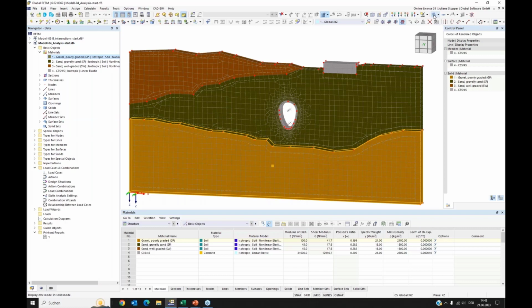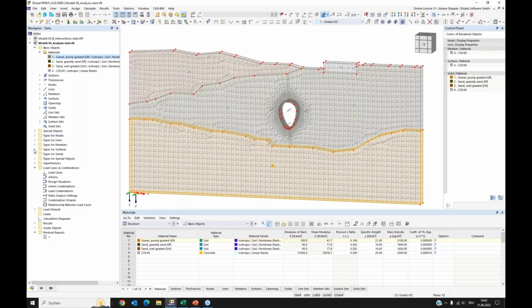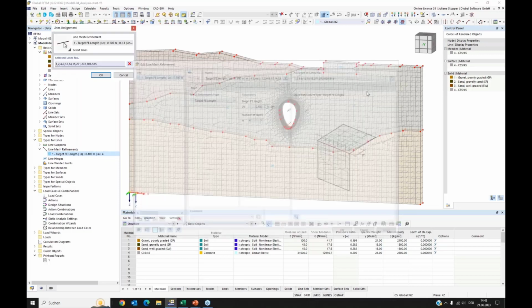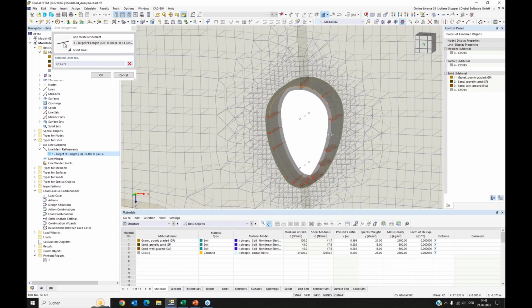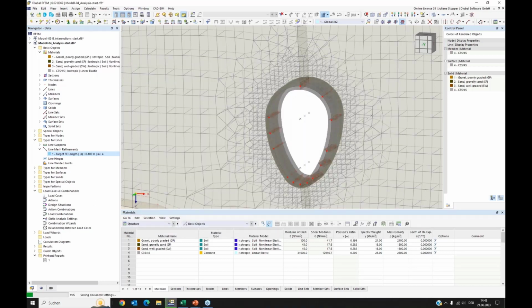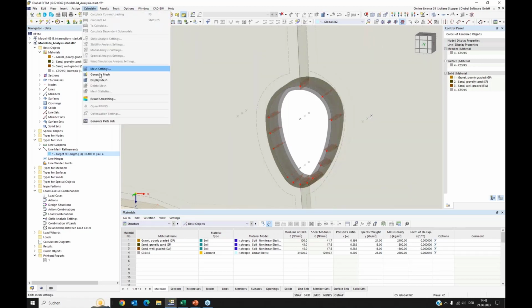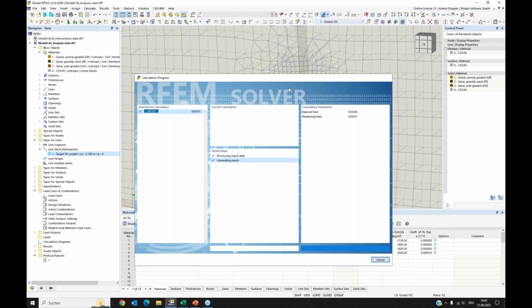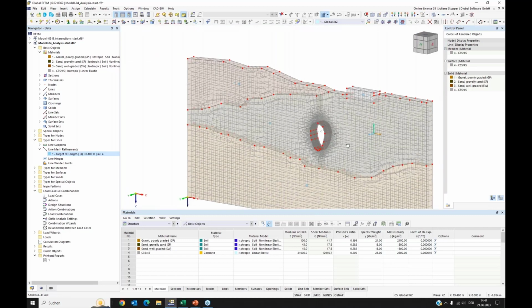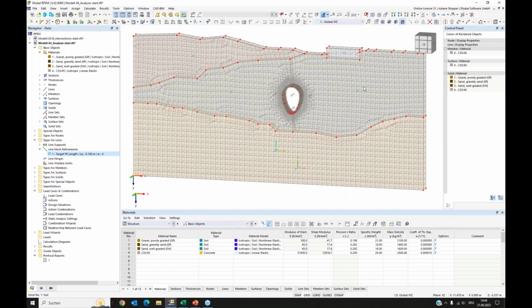Then I have mesh refinement used. You can find the refinements in the types. I used a line mesh refinement. When we have a look inside, here are the assigned lines. I only wanted to assign these lines because it's something nice. The layered mesh automatically extrudes it into the depth, so it's not needed in the next step to again assign the lines. With this one line it's done. Then all of the topology is prepared.